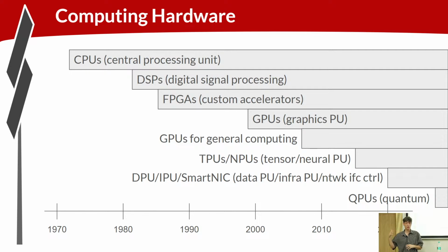This gave us a percentage improvement in performance, and that gave companies an edge. It also burned a lot of power. Some of the technology trends have taken us to a point where, first of all, power is a first order concern. Power impacts performance because you have a certain power budget. If your one core is burning a lot of power, you need to cut back on that by slowing down the clock and things like that. So everything is related. These big cores were power hungry.